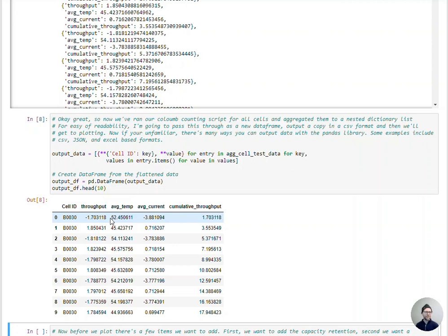So that's pretty significant, pretty interesting to find. Not too surprising that part of that would be due to a much higher current or load being applied to the battery. If you look, the load during charge is only around 0.7 amps. It's about a fifth to a sixth of the amount that's being applied during discharge for this particular battery.